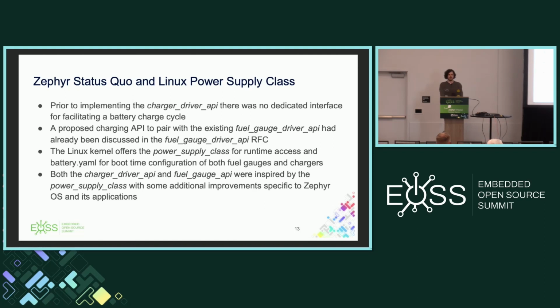So I got to cracking on it, and I took quite a bit of inspiration from what exists in Linux. For those of you that may not know, in Linux there's a power supply class that provides runtime access to both chargers and fuel gauges, as well as some boot time configuration for fuel gauges and chargers.